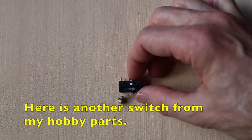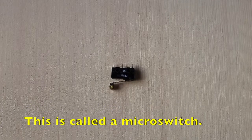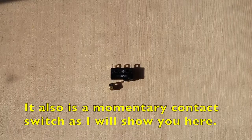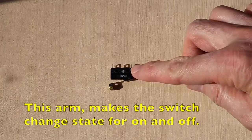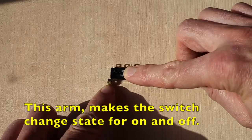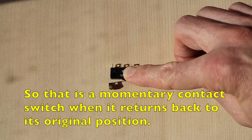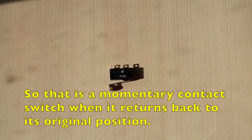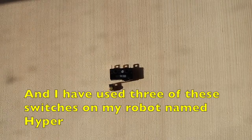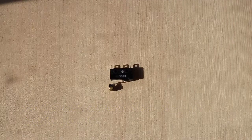Here is another switch from my hobby parts, and this is called a micro switch. It also is a momentary contact switch. As I'll show you here, this arm makes the switch change state for on and off, and it springs back. So that's a momentary contact switch when it returns back to its original position. And I have used 3 of these switches on my robot named Hyper to detect where the edge of a tabletop is.